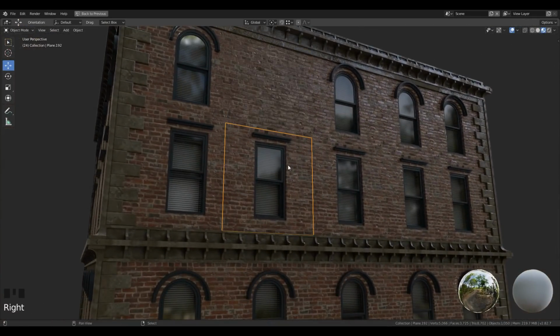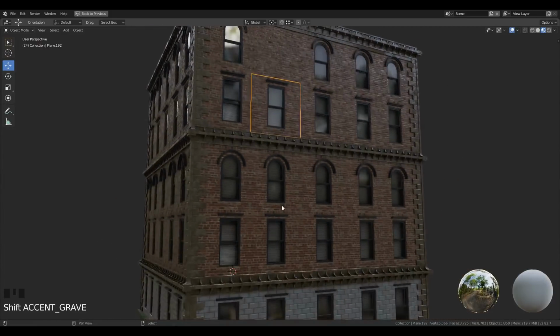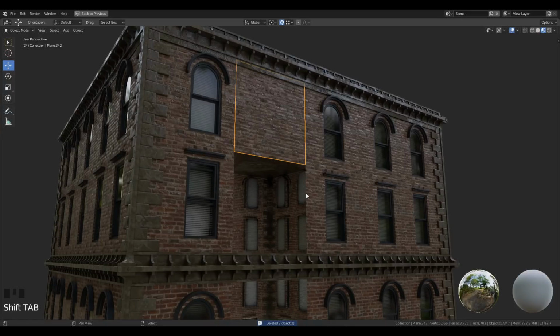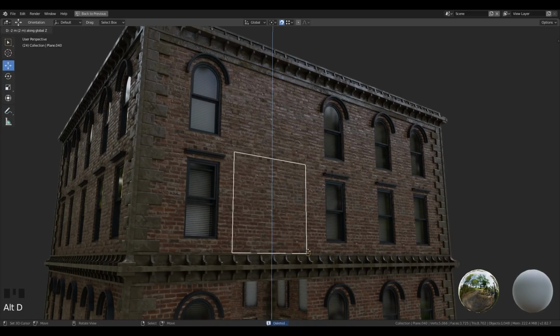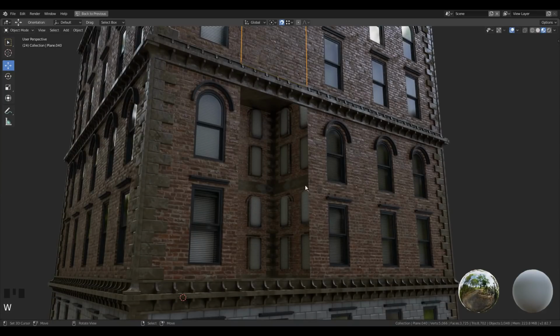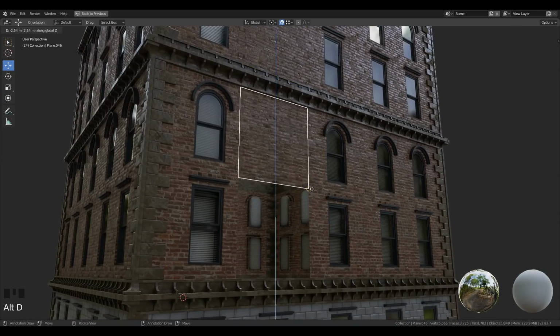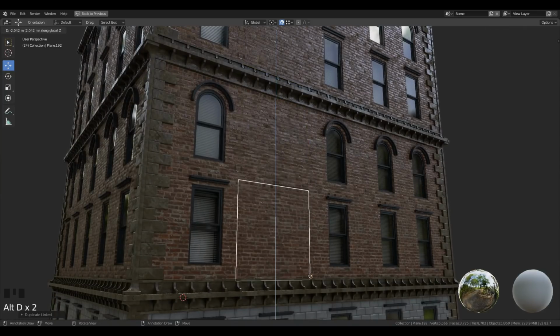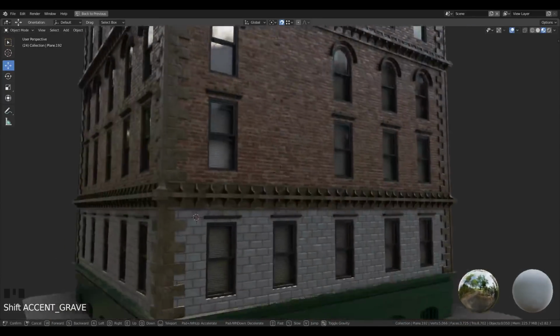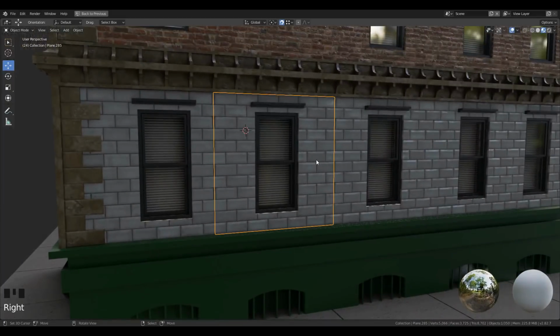After that, just delete the other meshes below this wall panel and duplicate an instance and move it with the snapping tool on to snap it on every corner of the other wall panels. Then you will need to repeat that for the window below.